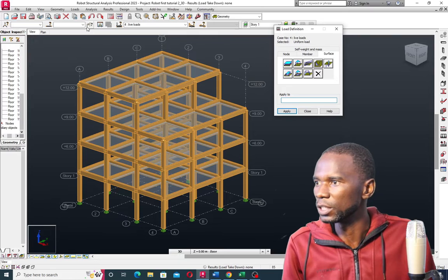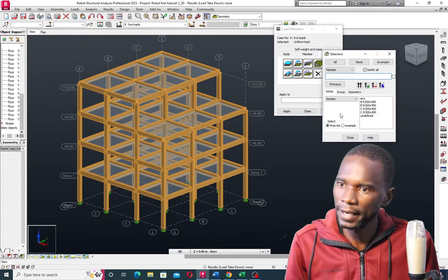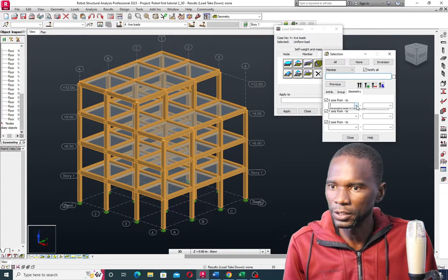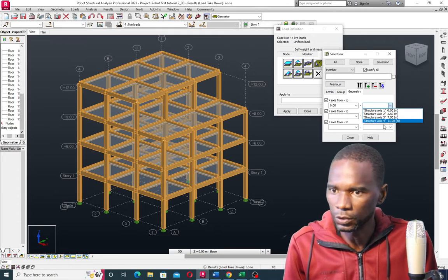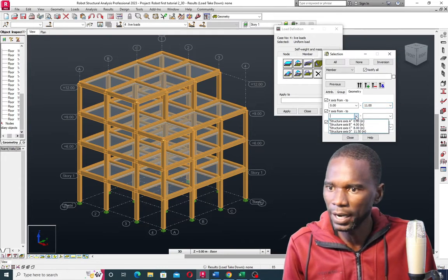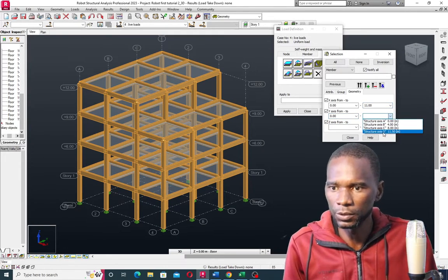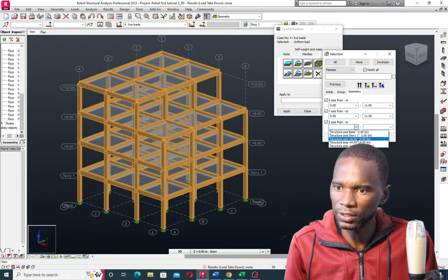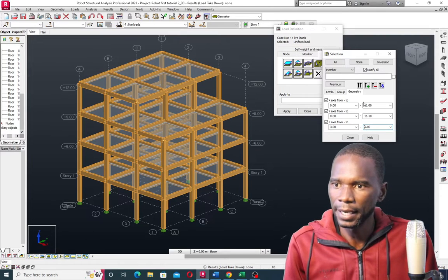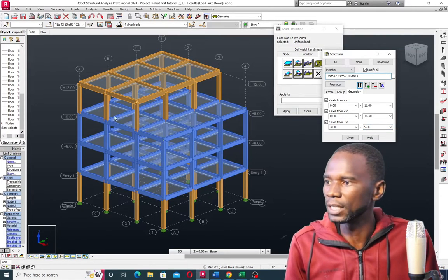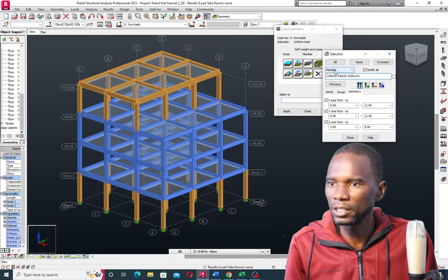But what I'm going to do is to simply go to the selection there. Again, I'll use the geometry axis, meaning from 1, actually from that one up to 4. That's okay. Then the Y from A up to D. The Z, I want to start from story 1 up to maybe 9. And add it there. As you can see, I've selected, but make sure that you don't pick the member, but in this case we want the panel.